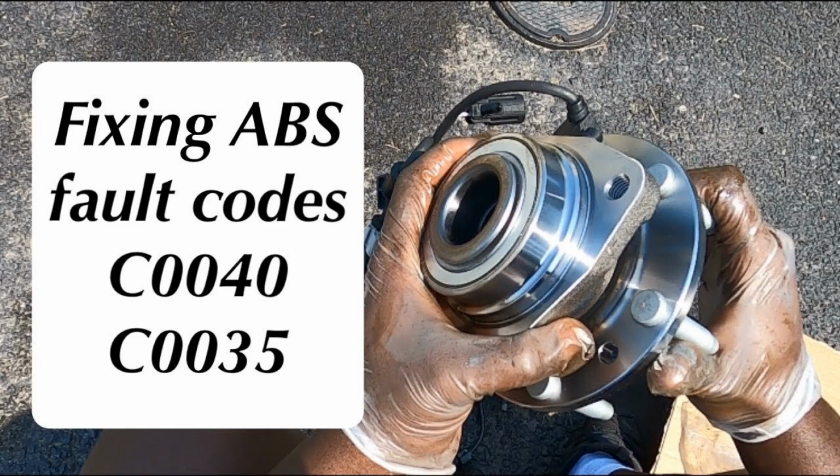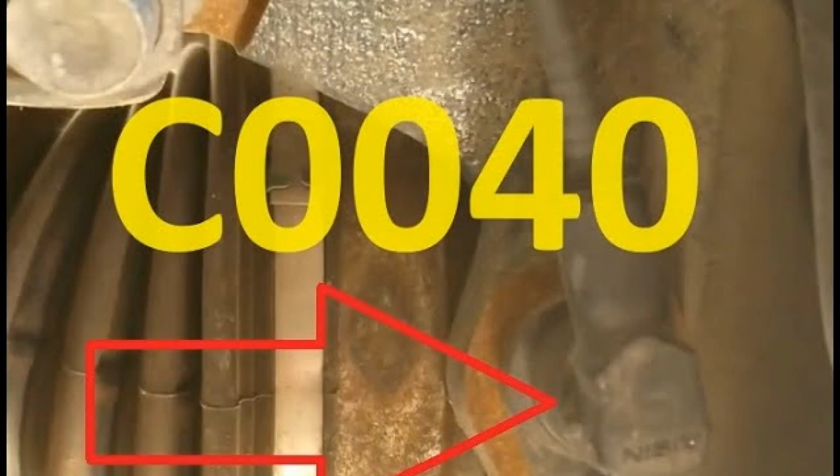What are the possible causes of code C0040? In fact, code C0040 can be triggered for a variety of reasons. Here are some of the possible causes of fault code C0040: a defective wheel speed sensor. The wheel speed sensor may be damaged or defective, causing the system to malfunction and generate code C0040.